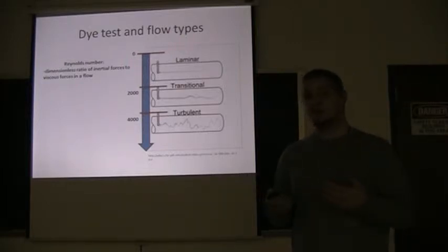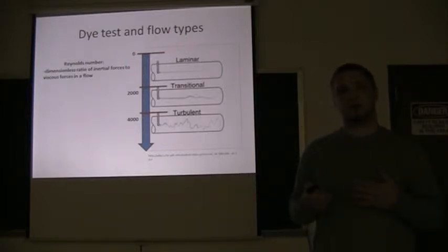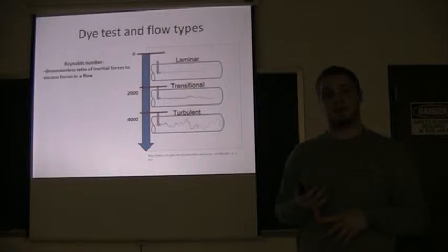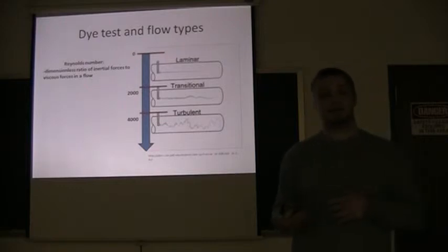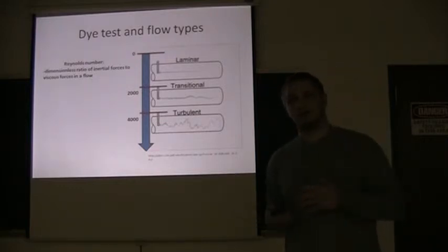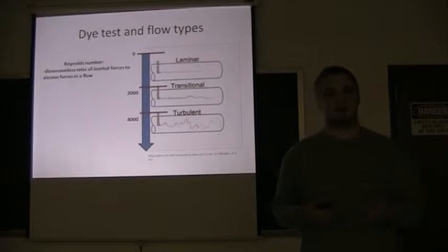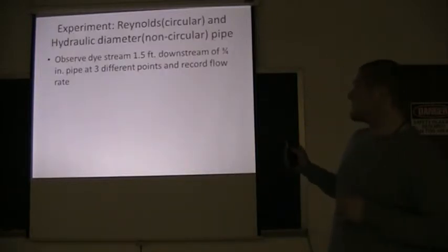So Reynolds number, it's a non-dimensional number. So it's very useful when you're trying to size the pump, like I said earlier, or when you're trying to choose a pipe. Other reasons you would like to use it is for dimensional analysis, for different numbers like the Grashof number, and there's a few others in there that helps correlate all this data that you end up getting.